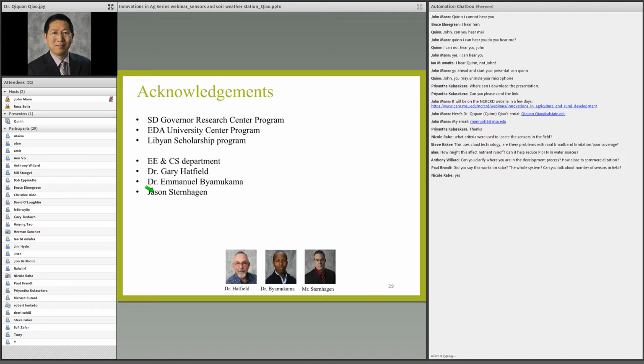But for the other sensor nodes located far away from the supernode, we use LoRa technology that doesn't need the internet because it is based on radio frequency. So we don't need any internet across the field. We just need it in one spot to send collected data from other sensor nodes to the cloud.